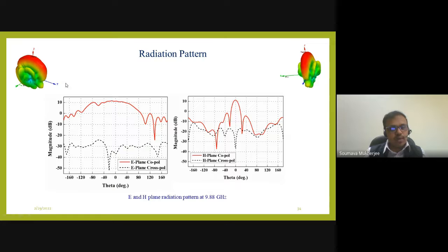This same radiation pattern cut in ZY will look like this in the 2D scale. The same radiation pattern cut in the ZX plane will look like this in the 2D scale. So antenna engineers need to understand from these two 2D curves what the radiation pattern typically will look like in 3D. And from there they can predict what is happening.